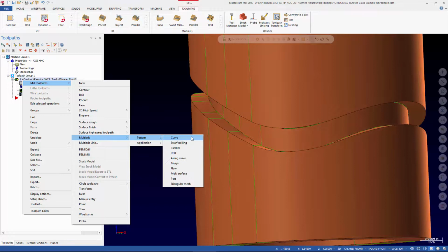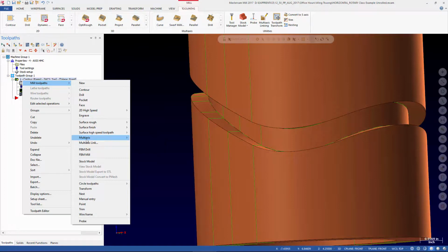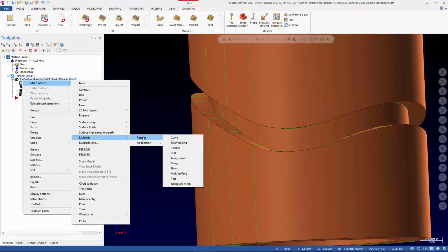And eventually that tilting vector gets converted by the post processor into rotation. So multi-axis can for sure drive this, but there are some non-multi-axis paths that will also cut this shape. The limitation with using the multi-axis is that you have to have the multi-axis license. So we're going to look at a couple of different options.